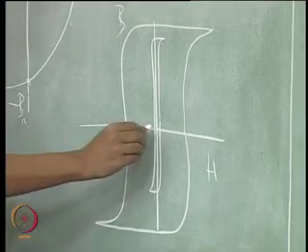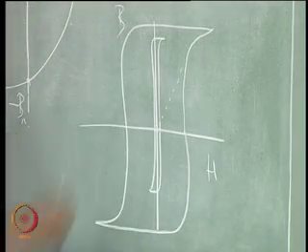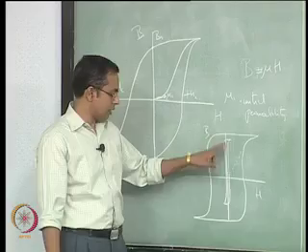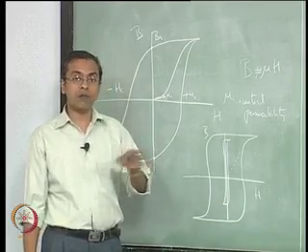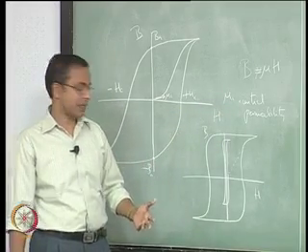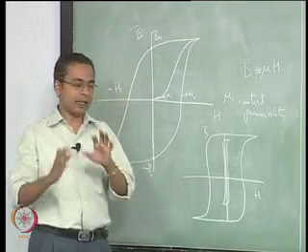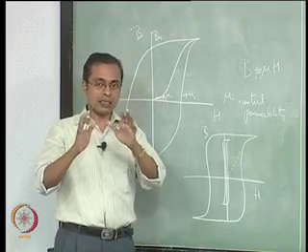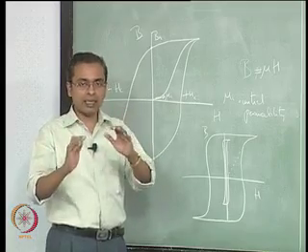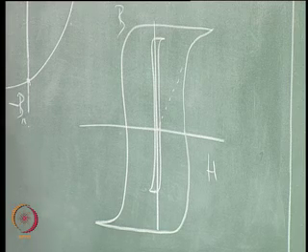Okay, so here in terms of initial permeability, if you are looking at this direction, it is a lower initial permeability and high coercivity. The inner curve here is what we would describe as a soft magnetic material. A material displaying the outer curve is what we would call a hard magnetic material. So for magnetic storage, a hard magnetic material would retain, once it is subject to some magnetic field, a certain state much better. Even with some changes in its environment, it will retain that state. You have to make significant changes to its environment before it loses its magnetization.